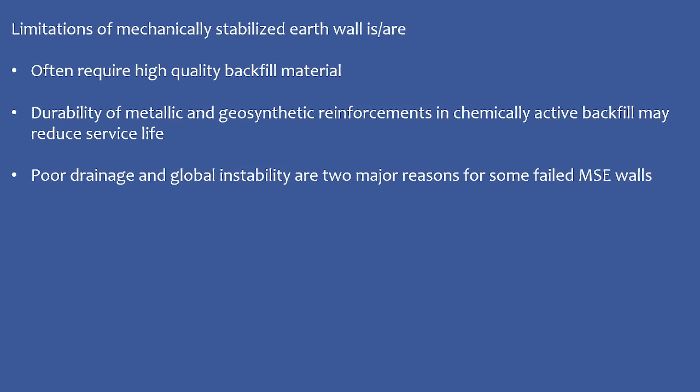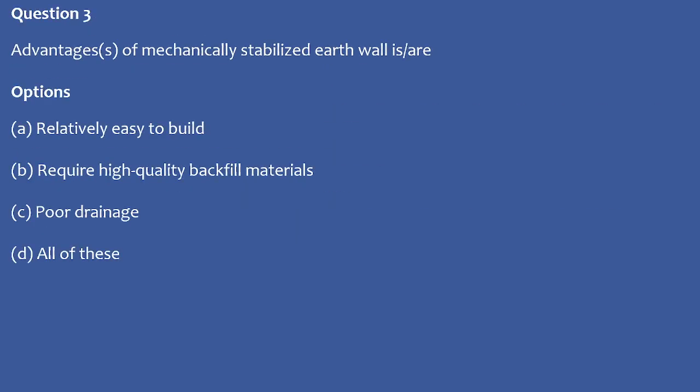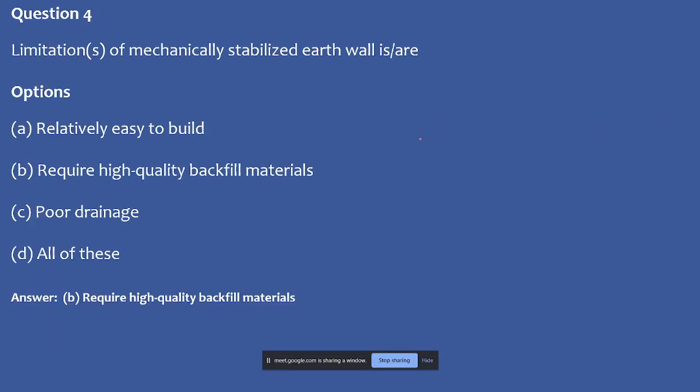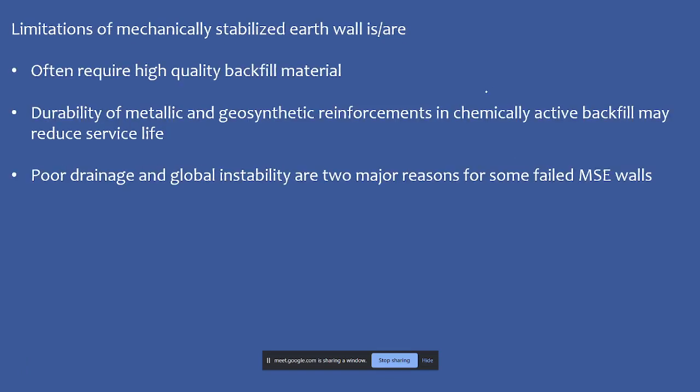Other limitations, if we can see, it often requires high quality backfill material. We have already discussed it, and the durability of the metallic and the geosynthetic reinforcement. When we have the mechanically stabilized earth wall with the compacted fill, the reinforcements also have their durability.